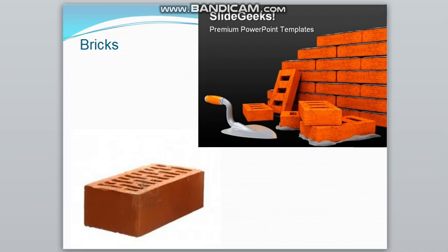Generally, one of the important tests performed on bricks is the water absorption test. According to Indian Standard 3495 part 2, dry bricks are put in an oven at a temperature of 105 to 115 degrees centigrade till they attain constant mass.